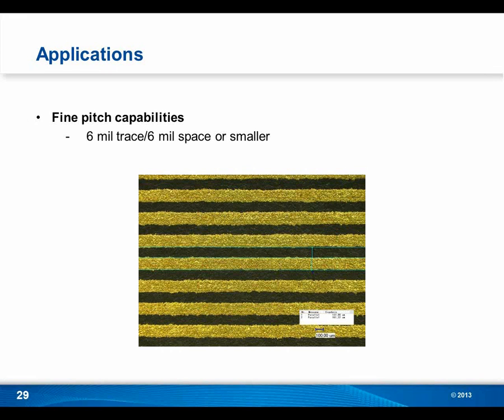One question we just got in from John, looks like he sent it in just a couple minutes ago. He wanted to know if the circuits can be sealed after plating to protect against exposure to moisture. Actually, I've seen some applications that do this, where once the circuitry is formed completely, there's a coating layer going on top of the entire part, which can be for aesthetic purposes or, like I said, for protection from moisture or any kind of environmental influence. So yes, coating on the plastic part can absolutely be done after the circuitry has been applied. Gotcha.